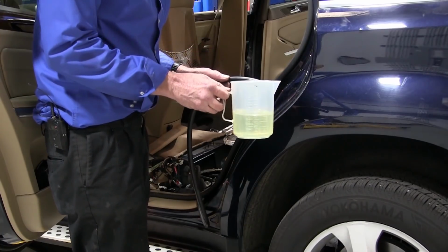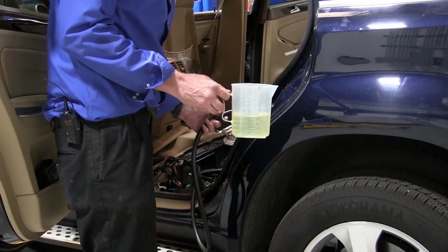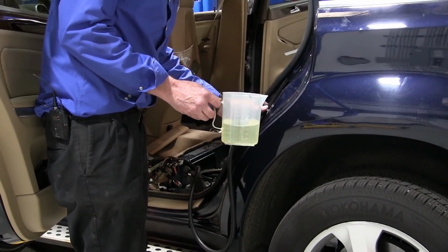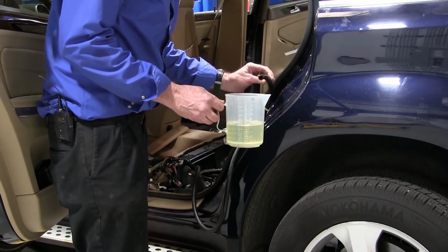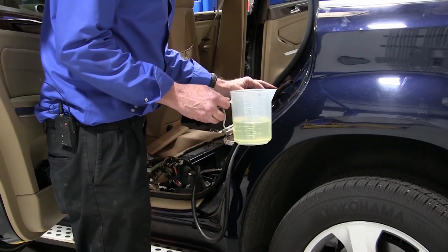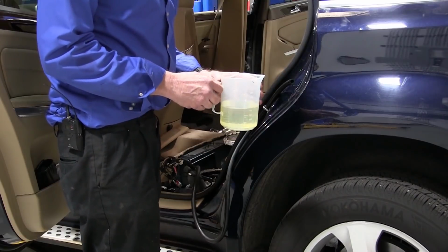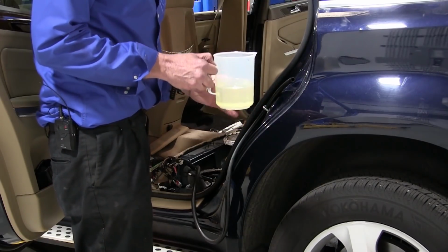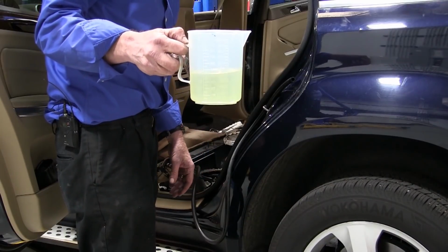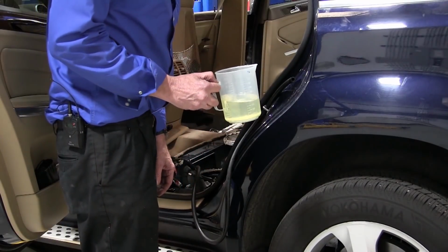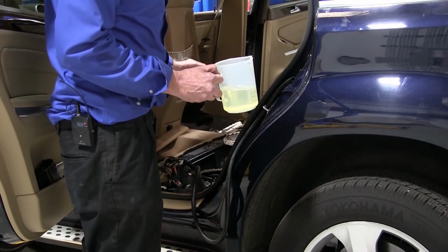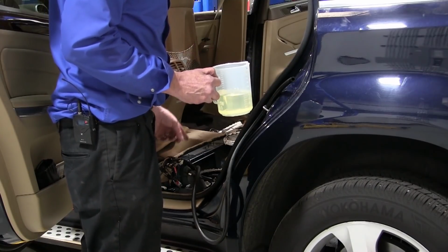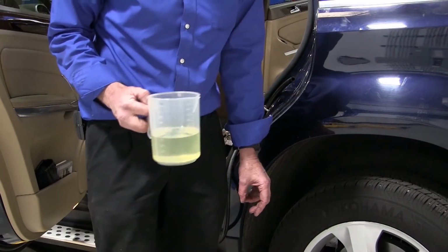We're getting half of the fuel delivery out of the outlet. Now when we came directly out of the pump, it filled the container totally within the 15 seconds. That's 15 seconds, and you can clearly see that it's half. So we have a restriction, and it's got to be in the crossover from the pump to the outlet, because that's the only place it can be now.